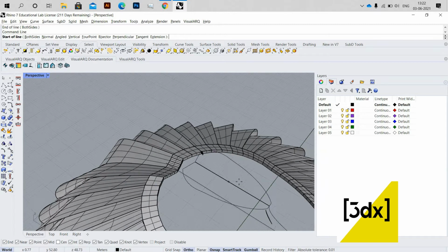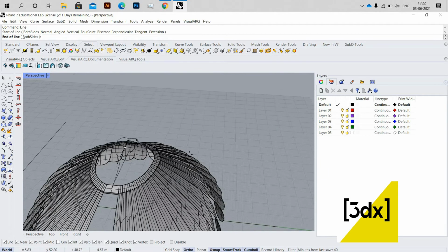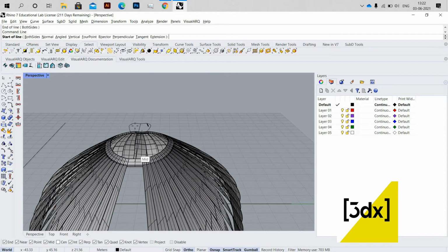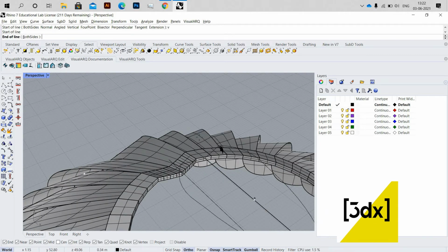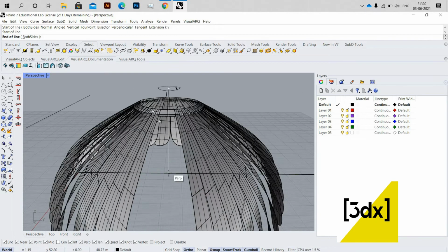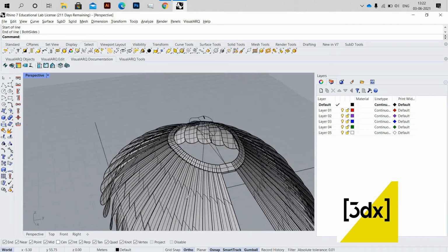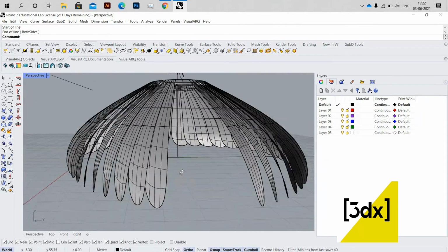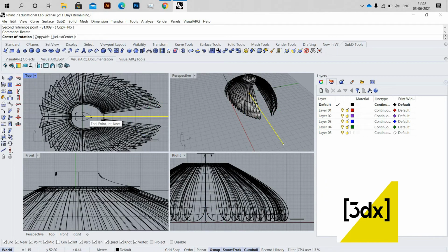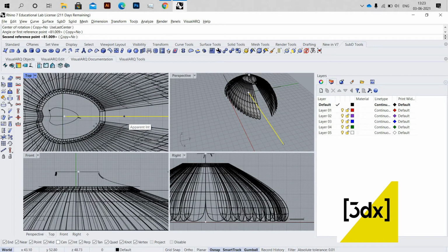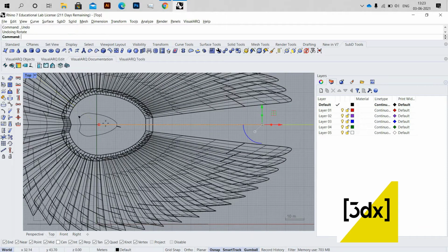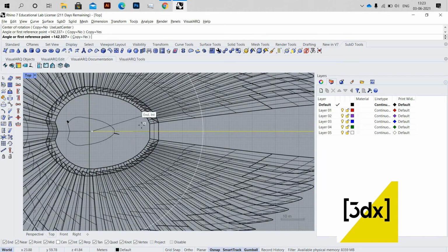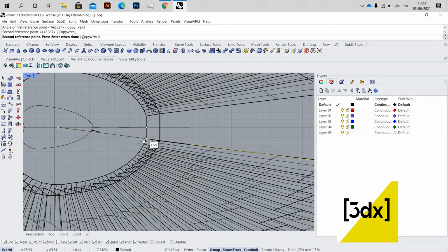So now I'm using the vertical line option. So now I just use normal. So line, I'm clicking the vertical line option. So I got the line. So this is fine. So I'm clicking the line. Now I'm rotating it. While rotating, I'm pressing copy yes, so that whenever I place the line, it will create a copy.